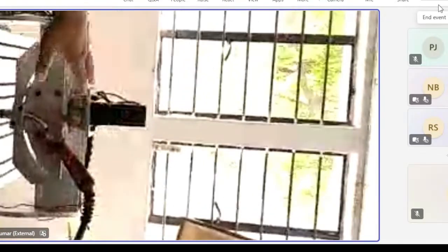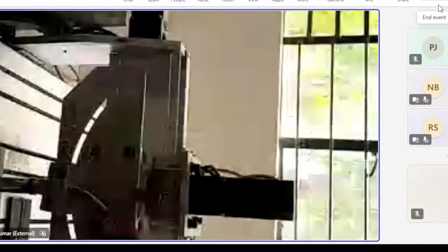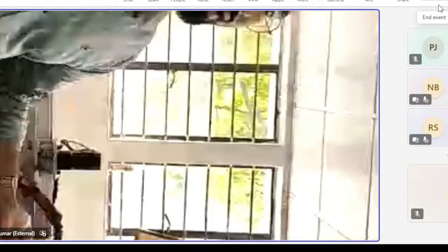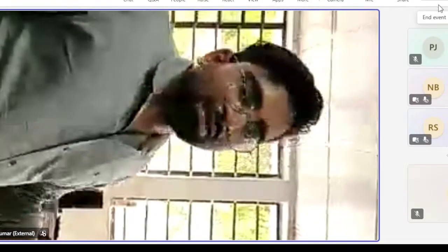So for that, the most important thing before starting the process is that you have to check the nozzle to standoff distance, the nozzle to surface distance. It should be in the range for operating the experiment. Another thing is the process parameters that you are choosing here. As per our trial experiment, we got some ranges from 22 volt to 26 volt for this specific material, SS308N. So here I am showing you 24 volt as one process parameter.